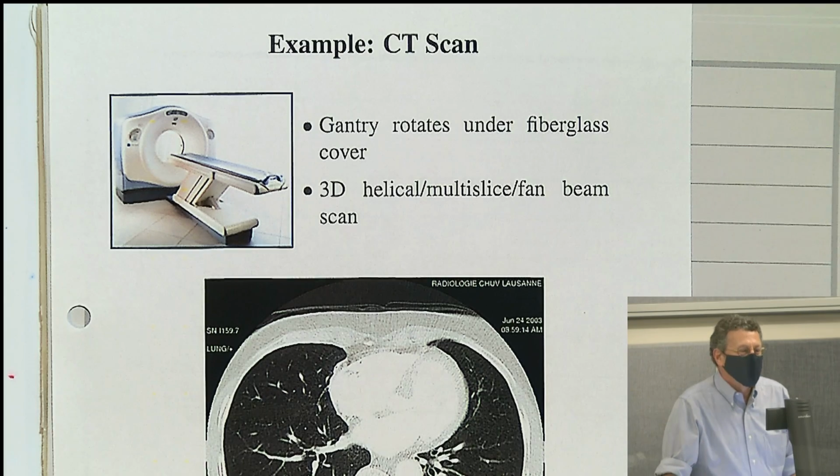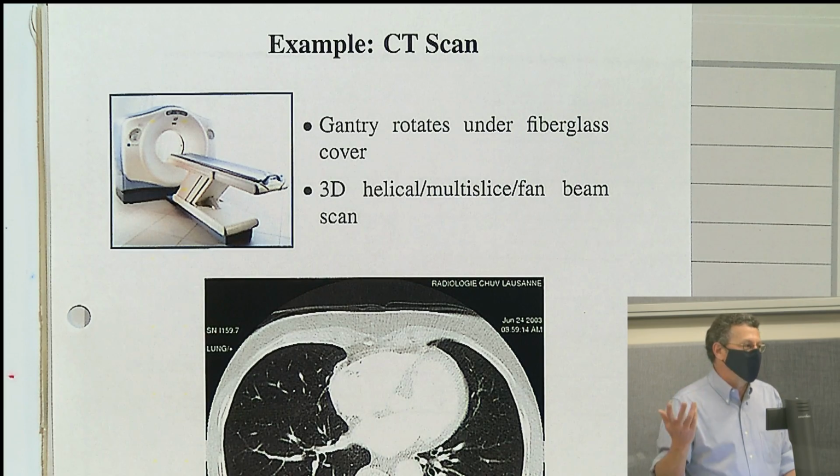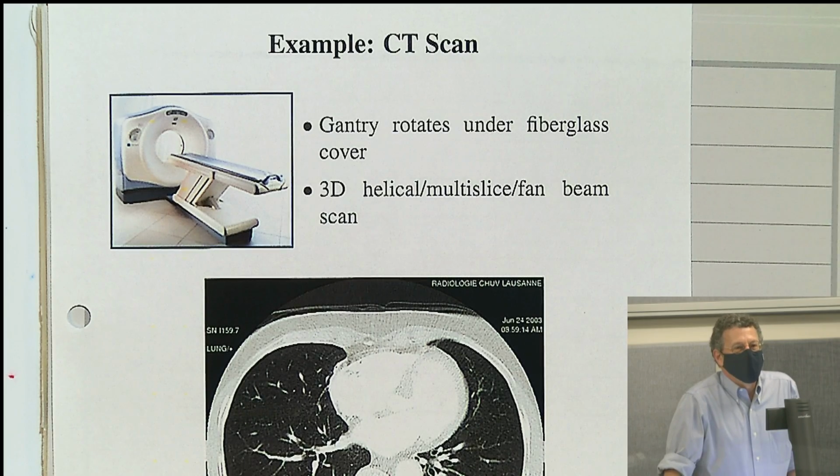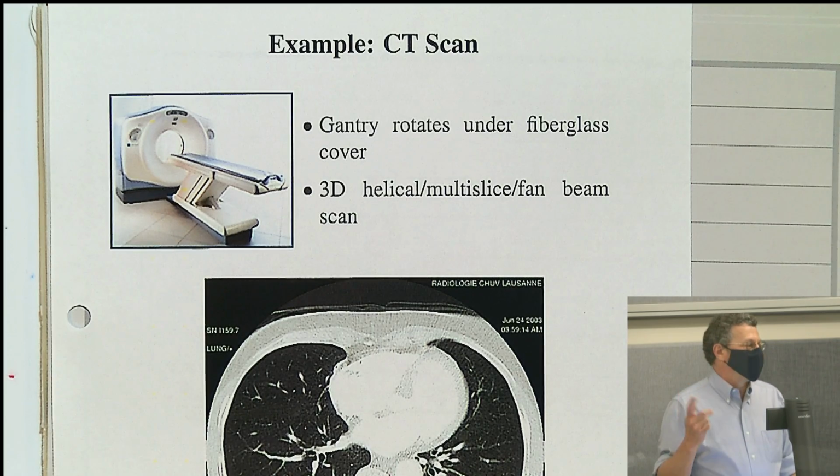They're incredibly sophisticated with the cooling mechanisms that they use and so forth. So they have to make sure each one of those fan blades is very precisely manufactured, because if it shatters in the engine, that's bad. That's an engine failure, which of course you don't want. So they inspect those, and they have to inspect them with CT, okay?